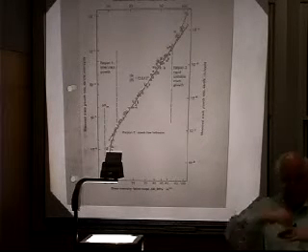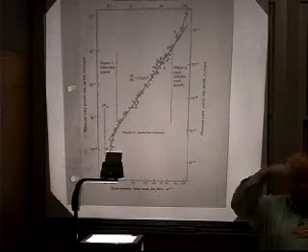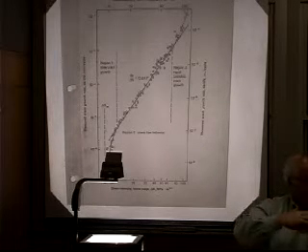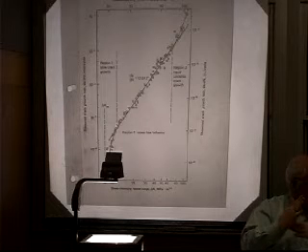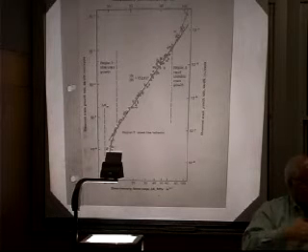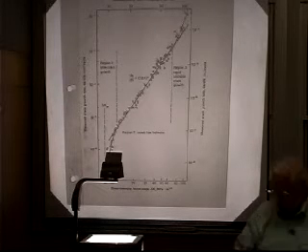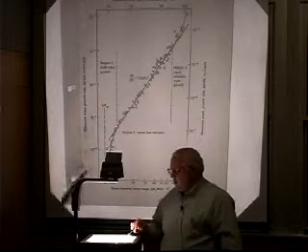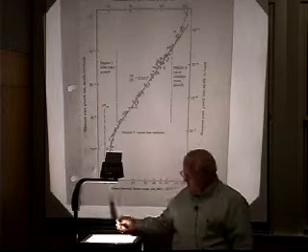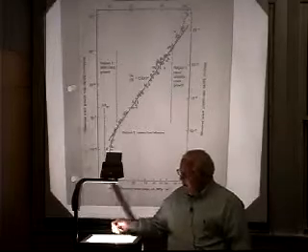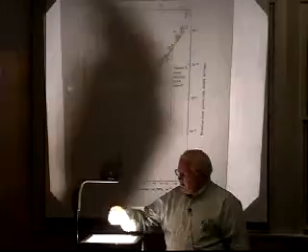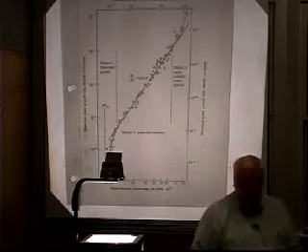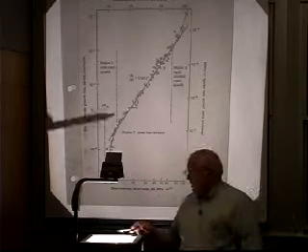So another thing, people use electrical on metals. They use electrical resistance through the thing, passing a current every now and then, and the cross section that remains has a higher resistance than if it was a larger cross section. So you use electrical potential drop. You measure the crack growth rate per cycle, and you plot da/dN versus stress intensity, and you get this type of crack growth rate curve. This is the proper way to do it.